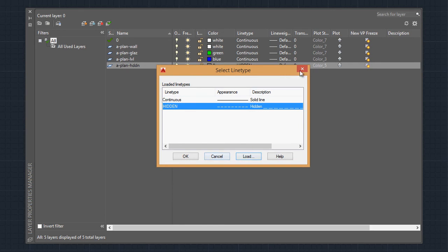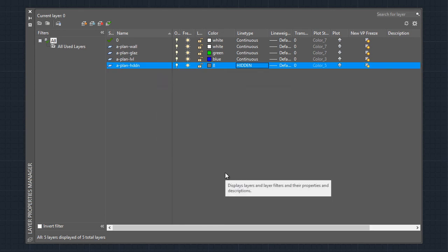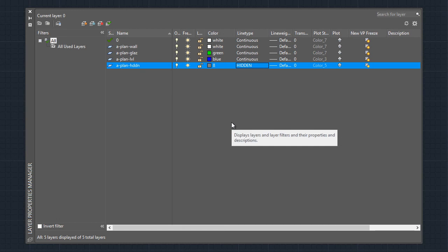And also note that the layer characteristics are universal for all of the objects that are assigned to that layer. So by changing the settings in the property palette or under the properties ribbon, you can assign different characteristics to an object. So in other words, you can customize an object individually to be different from those of the same layer. But there's a time and a place for that, and it's few and far between. So this comes from experience using the program, especially in conjunction with a project. So in time, you'll recognize when to do that, but refrain from doing that in this class. It can have severe repercussions that are not immediately obvious to a beginning user.